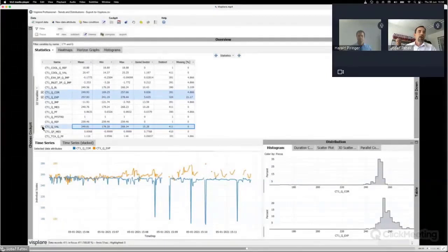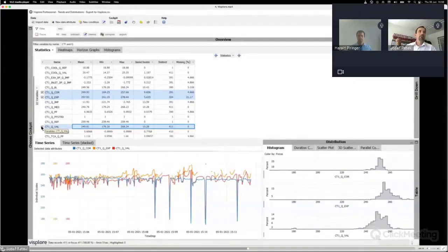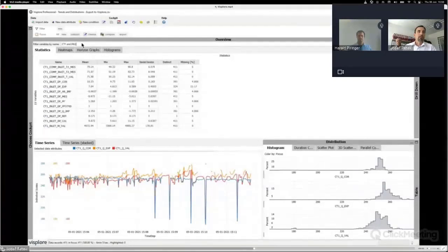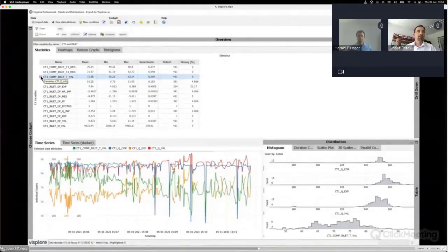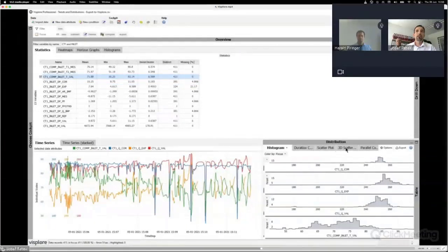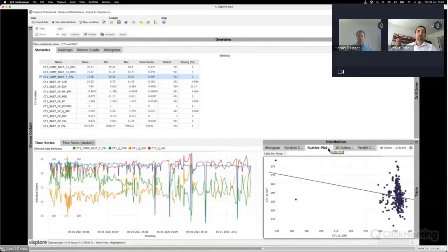In order to verify the models, it makes sense to put independent parameters as well. What are the independent parameters for a gas turbine full load situation? The most impacting parameter would be the set of ambient conditions, and out of the ambient conditions, the temperature has the most impact. So therefore, I add inlet temperature as well. And now I have my parameter set prepared to start with data analysis, and I do that using a set of scatter plots.